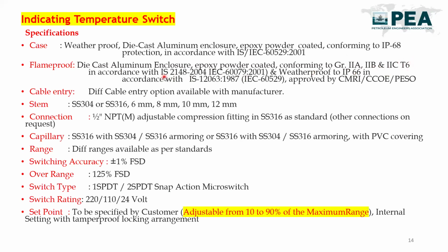We will need to specify all these flame-proof apparatus requirements while selecting this temperature switch, because hazardous area is a very crucial thing for the oil and gas industry. It is a big subject for the industry, because every industry has to keep hazardous area classification in mind, as a small hazard can make a bigger trouble or the biggest problem in your plant.